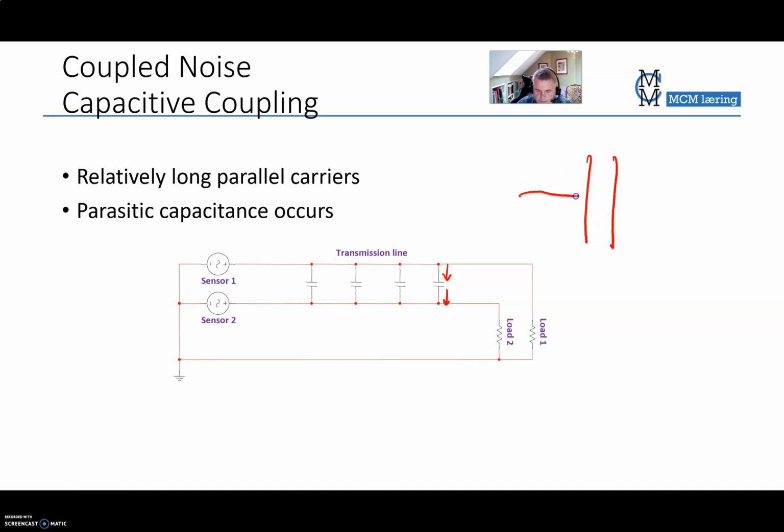First of all, you need two areas with conductive material, one area here and one area there. Second, you need a gap between them, a distance. And the third thing you need is to fill that gap with something that could carry an electrical field. But even vacuum works for that third element required to build a capacitor.